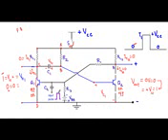We have applied an input pulse of brief interval and it has a high amplitude. After a short time the input pulse will come from its maximum value to 0 volt. As the input pulse has come to 0 volt, our capacitor C1 starts discharging through this path, R2, VCC, and the short path of the transistor Q1.